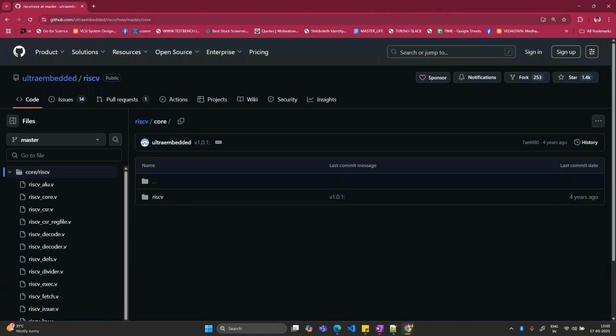With this Risc-V core, we will be developing one small accelerator. I build one small matrix multiplication architecture, which I put into this Risc-V core, and I show you how we can design various custom extensions on top of it. So that is one of the cores we will be looking at.